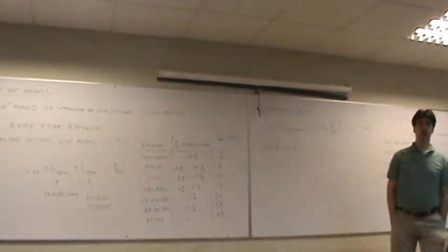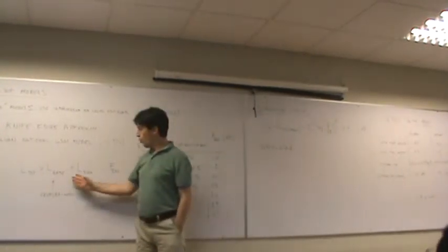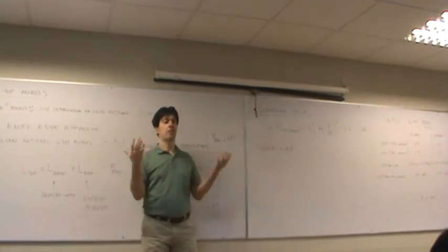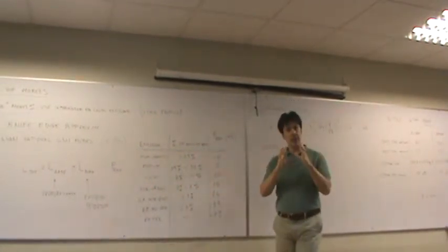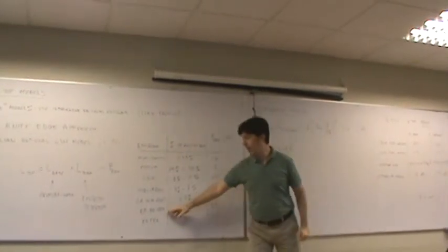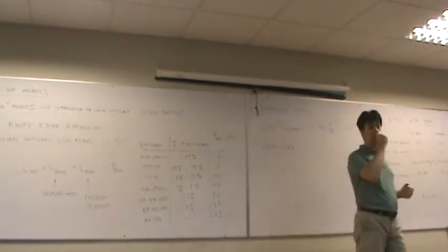That's a correction factor due to the fact that the Okumura-Hata model has been studied and developed for urban areas. So when you go to open areas, you have to correct the model's prediction.